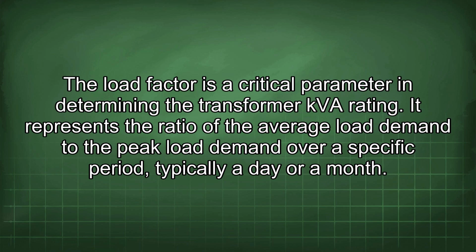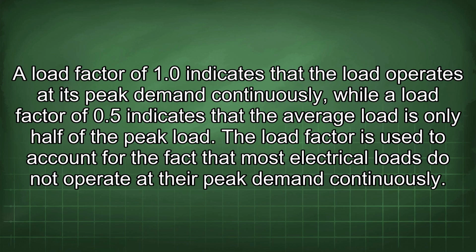The load factor is a critical parameter in determining the transformer KVA rating. It represents the ratio of the average load demand to the peak load demand over a specific period, typically a day or a month. A load factor of 1.0 indicates that the load operates at its peak demand continuously, while a load factor of 0.5 indicates that the average load is only half of the peak load.